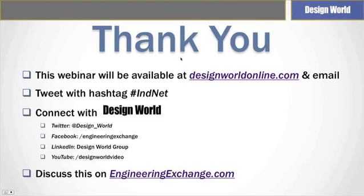EtherCAT is actually, one of the biggest growth areas is robotics. So humanoid robots, industrial robots. I think you saw KUKA, ABB are using EtherCAT in robotics. Especially industrial robots work very well because EtherCAT is hot connect, hot disconnect. So for an industrial robot, you can have the entire network be EtherCAT and have end effectors that get attached or detached from the robot itself, without having to go into any other operating mode.